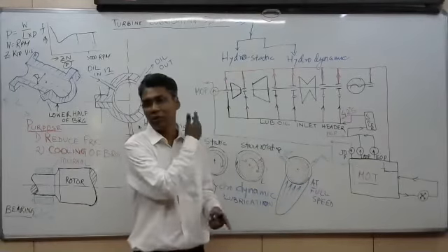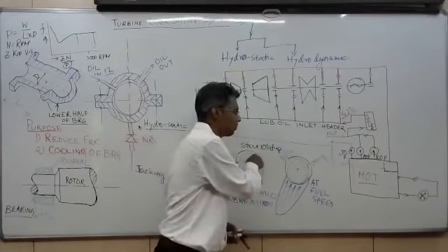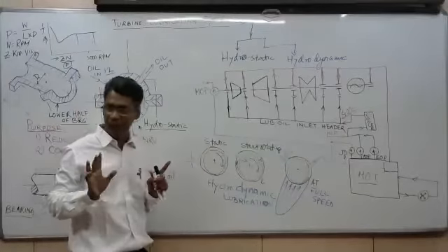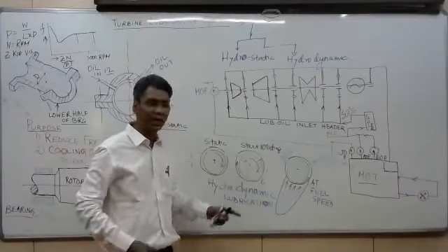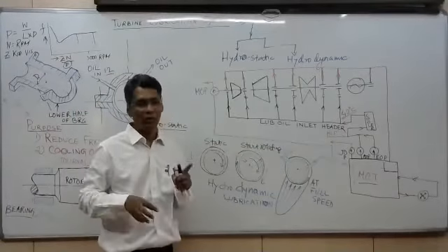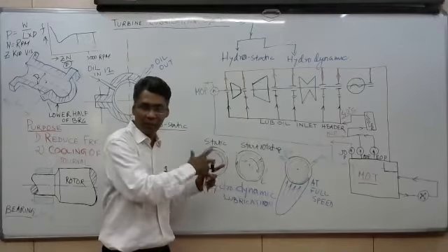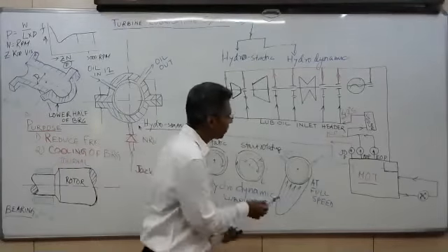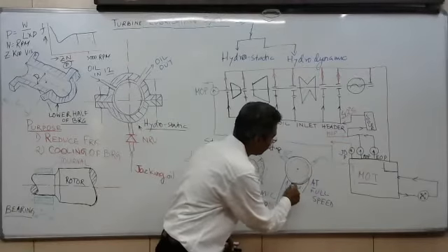So we have to remove this oil. Again, we push the fresh oil from here. So that's why 2 points are given, inlet and outlet. Right? So we are giving fresh oil and then it is pumping itself. We are not giving high pressure oil. It is pumping due to rotation. So the oil film is a continuously high pressure oil form.